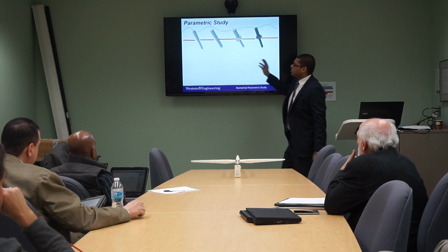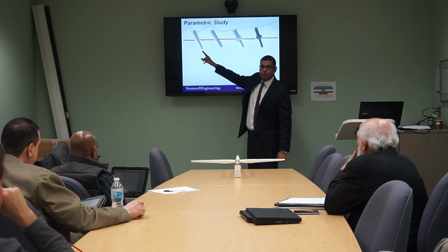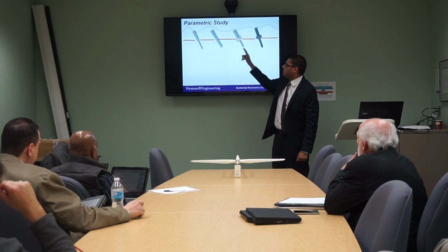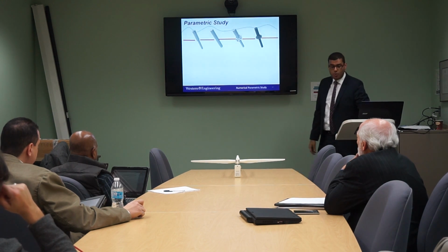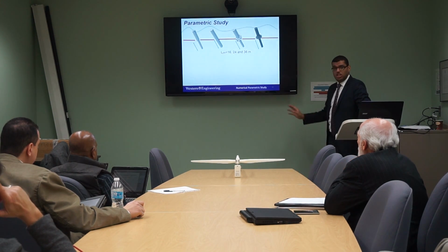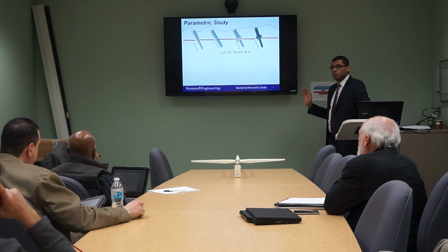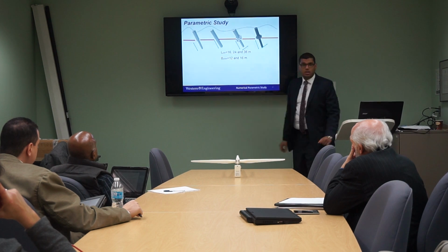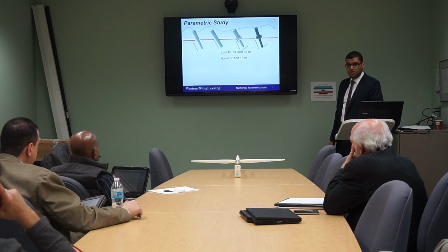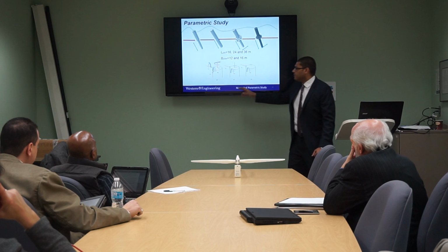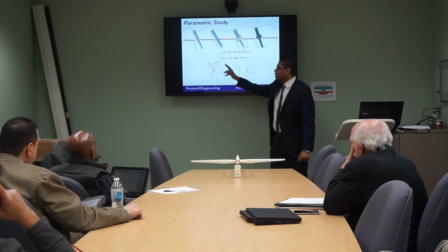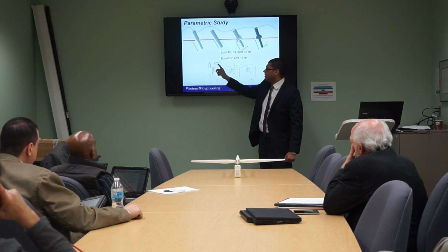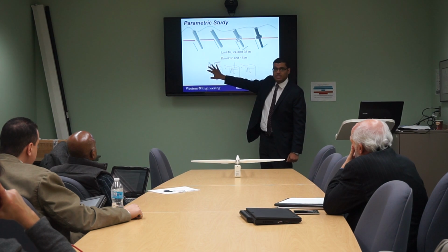So our different foundation systems: the monosteel pile 4 meter diameter, the monosteel pile 6 meter diameter, and our hybrid foundation system. We have done our parametric study by changing the lengths between 16, 24, 36 meter. We changed the blade diameter from 12 to 16 meters. We have done several load components: 6 components, 3 forces and 3 moments coming from the wind tunnel test.